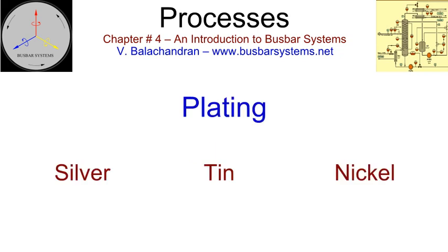Plating. A natural metal joint, made as per the recommended practice, is always preferable, be it between copper and copper or aluminium and aluminium. Such joints with boots and gel coats, to prevent exposure to atmosphere and ingress of moisture, have given satisfactory performance over the length of their life. International specifications permit higher temperature rise for plated, tin and silver joints, and consequently, it has become a practice to plate the conductors at the joints, thereby making the busbar system assembly more cost-effective. There are apprehensions on the life of plating and its performance under prolonged temperature cycles.